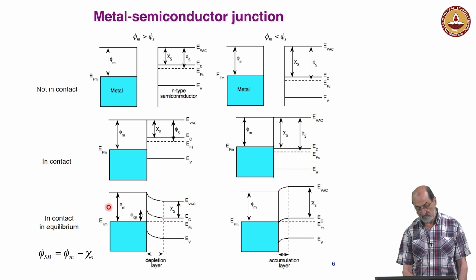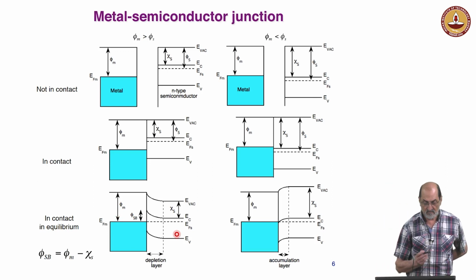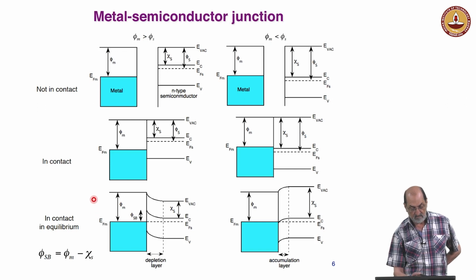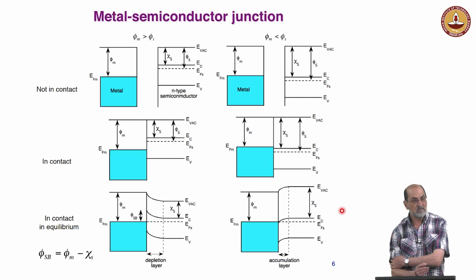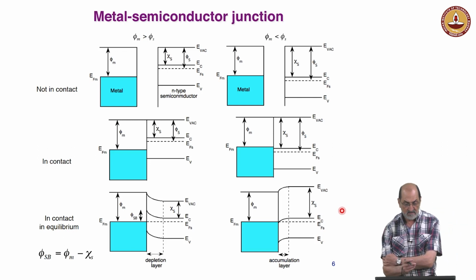If we do it the other way, a negative potential in the metal and a positive potential in the semiconductor, electrons always find the same barrier. It's more difficult for them to overcome the barrier. The barrier is not reduced in height. So it's easy to go from here to there, but not from the left to the right. So it's going to have a non-symmetric behavior. So this, in the literature, is known as a diode, the Schottky diode. Here we don't have a diode. Well, this is supposed to happen, and the difference,